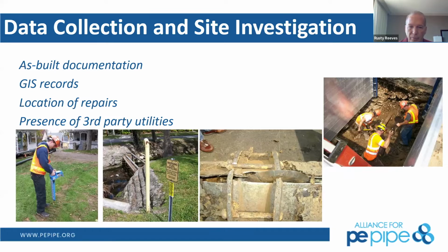You generally have a different material, and it's not that they can't be burst as you're showing there in the photo, but you definitely need to be aware of where those are. So again, the as-built, just like any project though, it's not very different from having to do an open dug trench. You got to know where those other utilities are. You got to know where your valves are. You got to know where these things are.